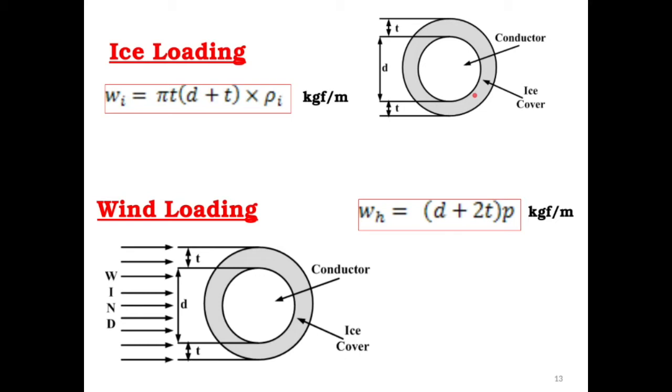Sometimes you will fail to count exactly how many strands are there. Each of them is called a strand, a single conductor. We put them together to increase the current carrying capacity of the cable or the wire. Each strand is circular, but when we use a number of strands to make a larger ampere capacity cable or conductor, it is no longer circular. But for simplicity, to make our equations simple, we consider that they are circular.